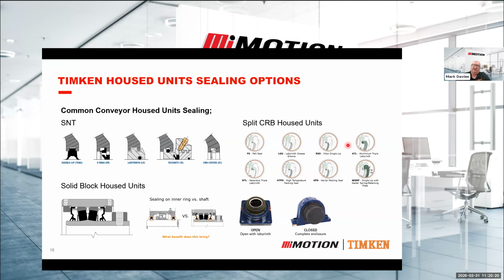So how do we seal that? Is there any way we can stop it getting in? Not really. There's all sorts of different types of seals on the market. Some very basic, like just a simple double lip grease seal. Others like the more common taconite type seal, which gives you a labyrinth to stop or slow the pathway of the contamination getting in.